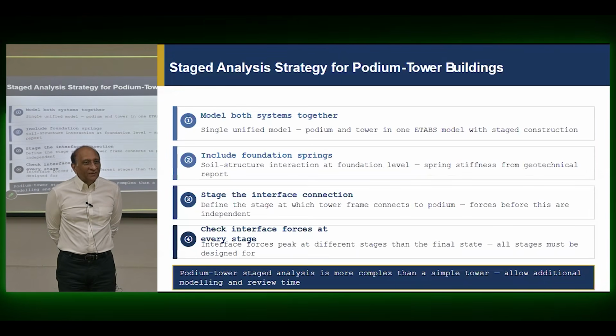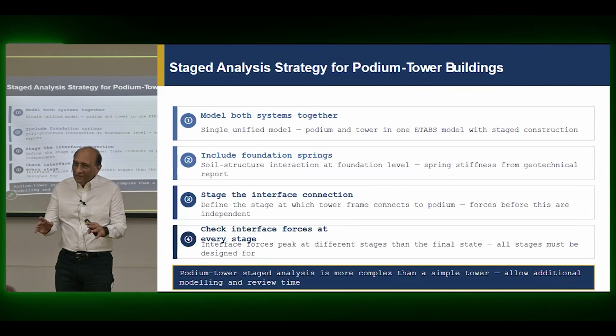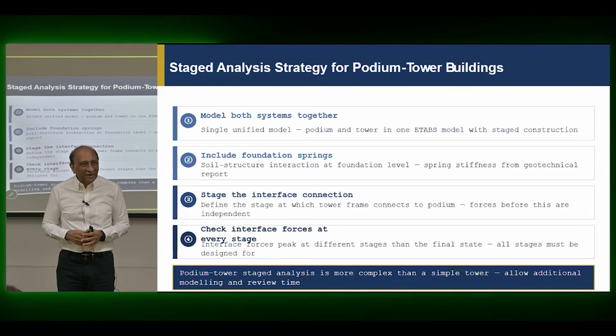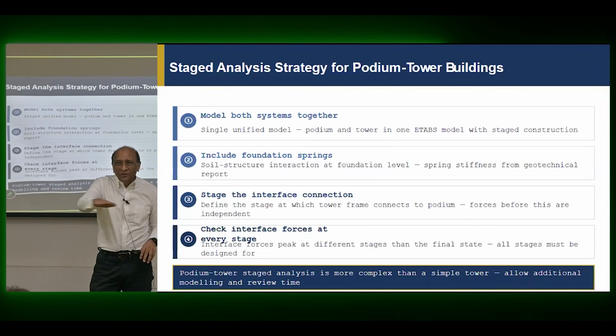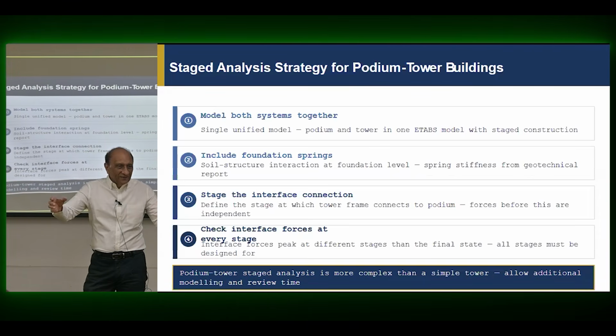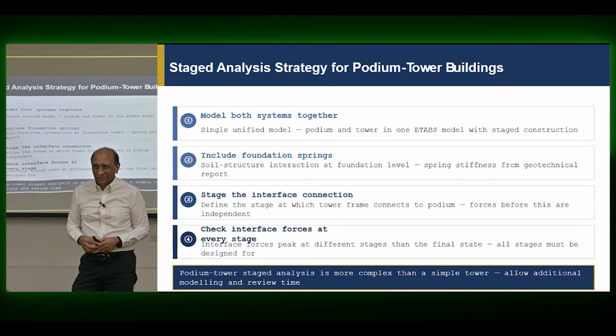My point is, we are just now taking it for granted that we can, because now ETABS has what is called a multi-tower modeling approach. The problem is, just 5 years, 10 years ago, ETABS did not have this idea of the multi-tower approach. So if you create one floor, it will consider that to be one diaphragm. No matter how many towers there are, they are assumed to be all connected by an invisible diaphragm.